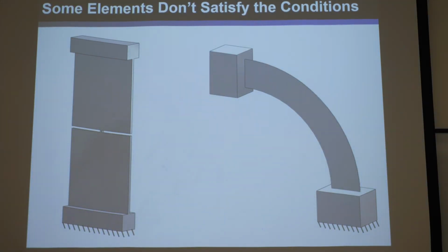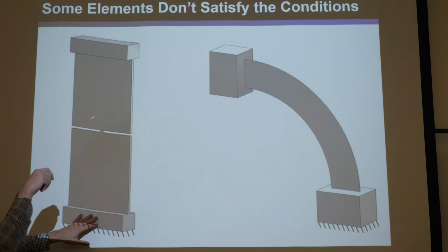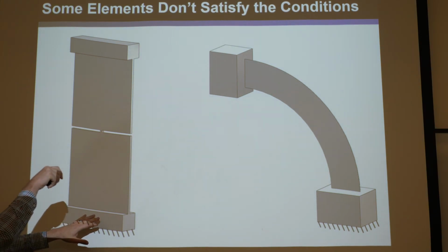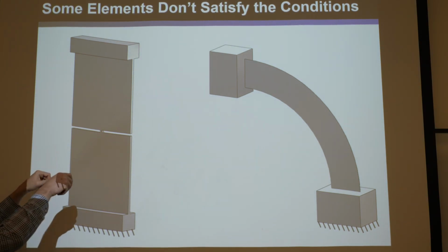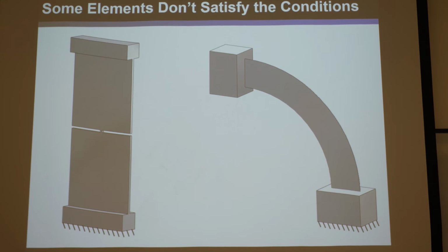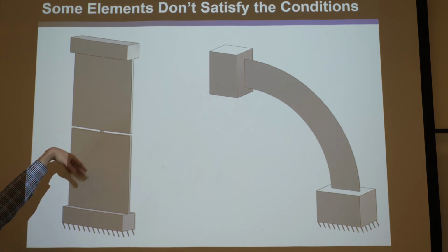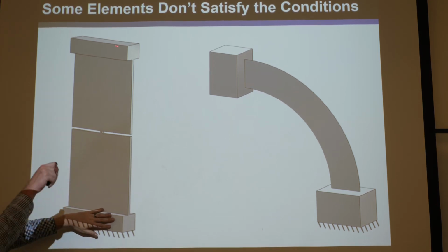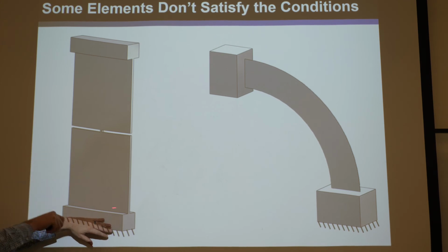So here you can see this whole thing is a compliant element. It's got a little notch cut. It's basically a blade with a notch cut in the side. This is, by the way, a very clever element that people use to not over-constrain parallel guide mechanisms. We'll talk about that in a second. But anyway, the point is, that's an element that deforms over its entire geometry. It connects two rigid bodies, as shown on this end and this end.